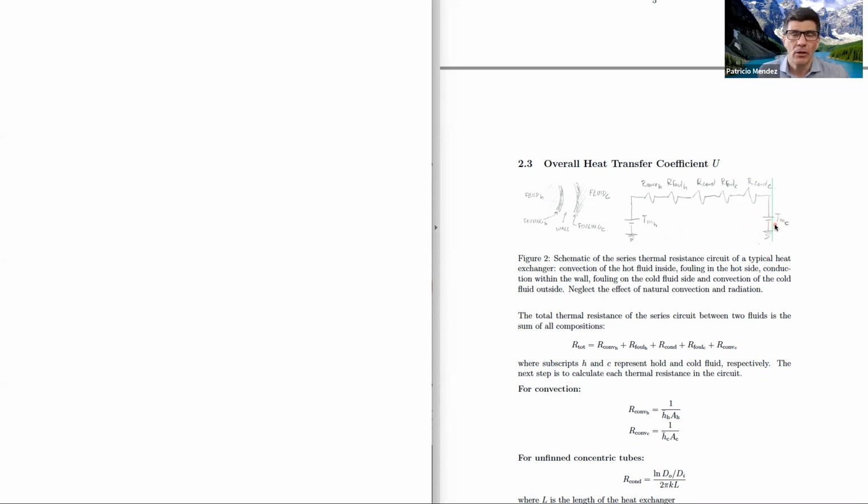If we're using oil or water, there's going to be no radiation. But if there is air, there's not going to be radiation either. And the reason is that for a heat exchange by radiation, we need two surfaces at different temperatures. And for example, if we have a pipe, we're assuming that all the inside of the pipe is at the same temperature, so there is no radiation inside. Similarly, if the pipe is outside looking out, typically it's looking at things of the same temperature.